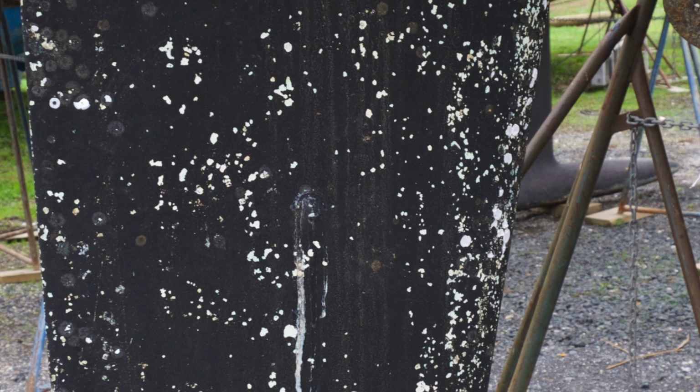So now that I know why the skin failed, I needed to design a way to prevent this from happening again. The strategy I opted for had 4 main parts. First, increase the rigidity of the skin. Second, use heavier foam. Third, mechanically anchor the starboard side of the skin to the port side and to the webbing. And fourth, allow for no large holes through the skin. We'll see in the next episodes how I implemented these ideas.